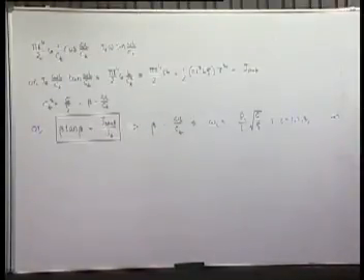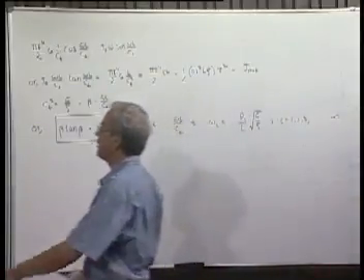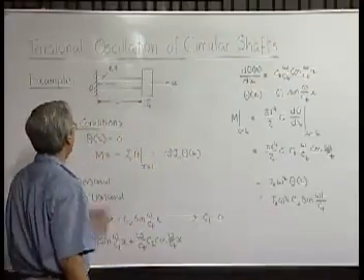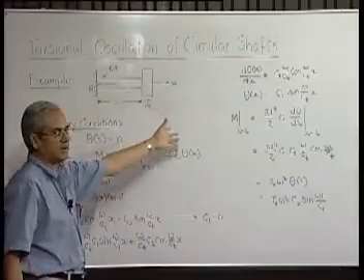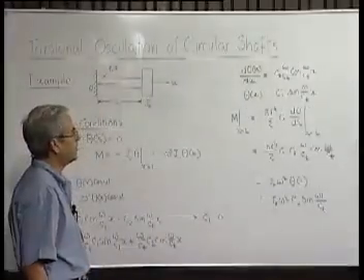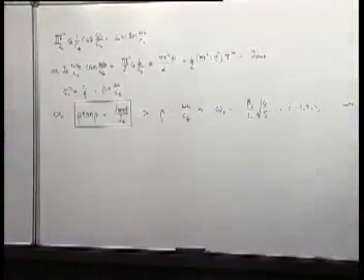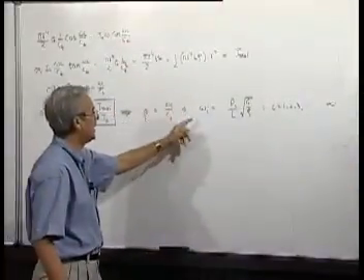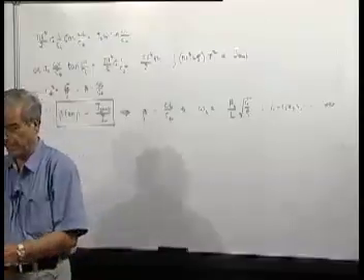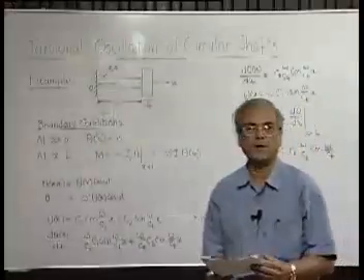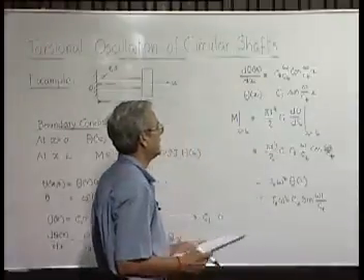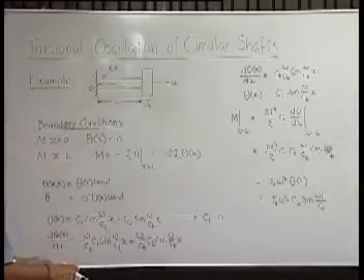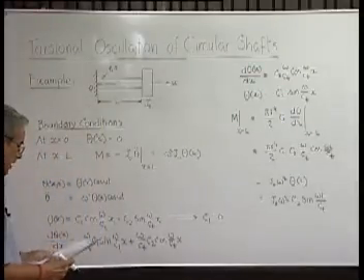So this is just an example. There can be another problem in which both sides of a shaft carry two disks, one with J1 moment of inertia, other side with J2, and the shaft dimensions are given, material is prescribed. We can find out again the equation, that means a transcendental equation we will get, and again solving which we will get ultimately the natural frequency. So thus we find that torsional vibration of shafts are very similar in its form and general form of solution, and equation of motion also, as in the case of longitudinal vibration of bars.